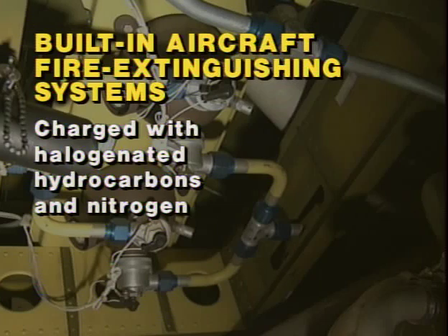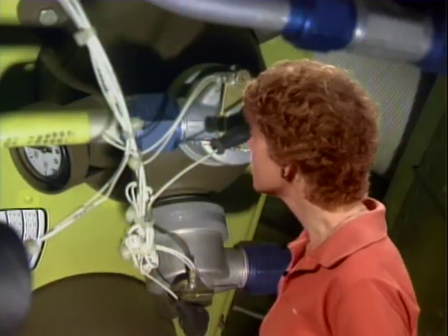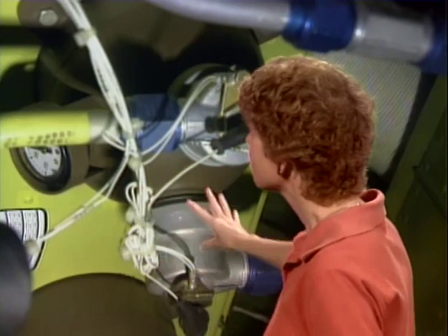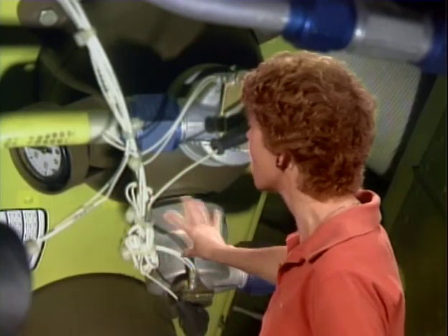Now, when you're looking at those fire extinguisher bottles, if a fire extinguisher cartridge has been removed from the discharge valve for any reason, it is strongly recommended that the cartridge be reused only on the original discharge valve assembly. And the reason for that is that the cartridge is not going to fit quite right on any other bottle because of the wear that it's had on it, and so you only want to use it on the original discharge valve assembly, or else it's not going to fit properly for the discharge.